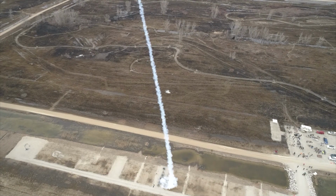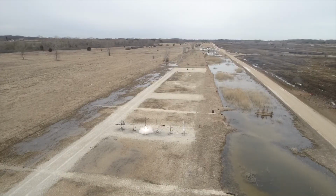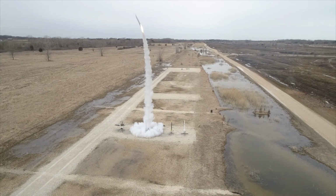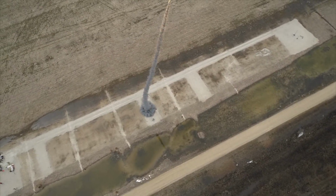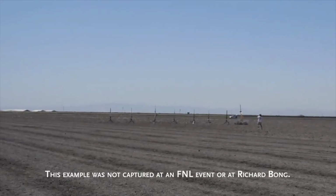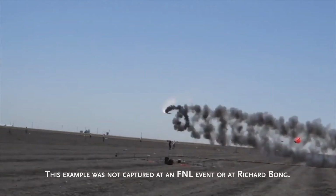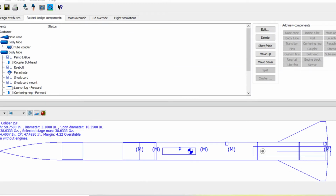A rocket that is stable will fly fairly straight, oscillating in reaction to the forces of wind and drag. A rocket with minimal stability will follow a flight path that is more erratic and reactive to wind and drag. And an unstable rocket may fail and begin flip-flopping through the air. Needless to say, this can be extremely dangerous. You will want to verify in RockSim that your stability margin is greater than 1 and that your center of gravity is forward of your center of pressure by at least 1 diameter of the rocket.